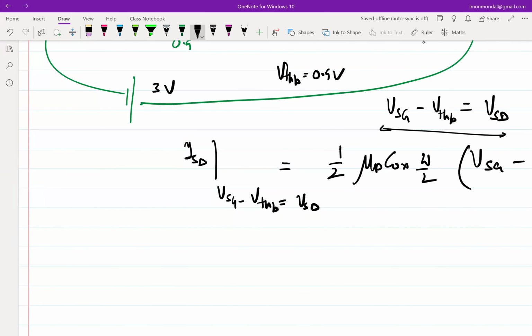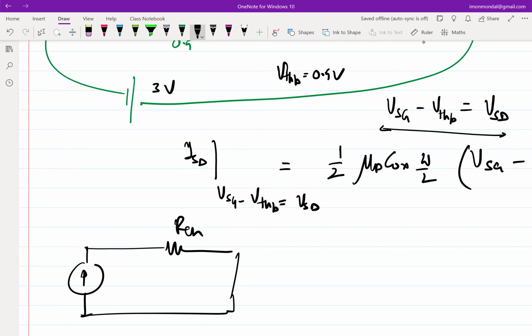Let's say I have a current source, and let's say this is the R channel, which is filled with mobile charges. If we keep on increasing the current source value, some voltage will drop across this R channel. But if I keep increasing the difference from the threshold voltage, I mean, keep going into this region where the channel has almost been cut off, then essentially this model is not valid anymore. There will be another model which will give rise to some R due to immobile charges.